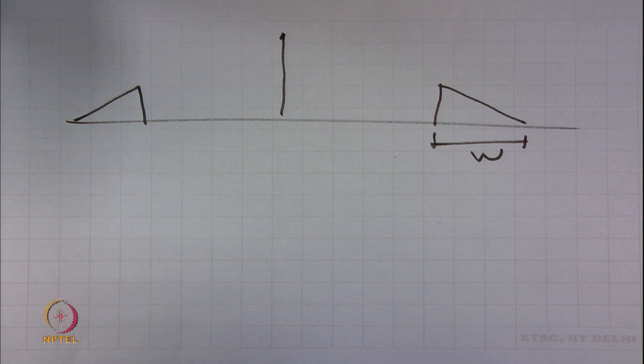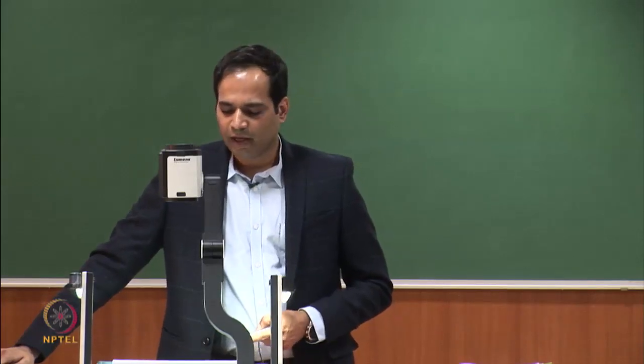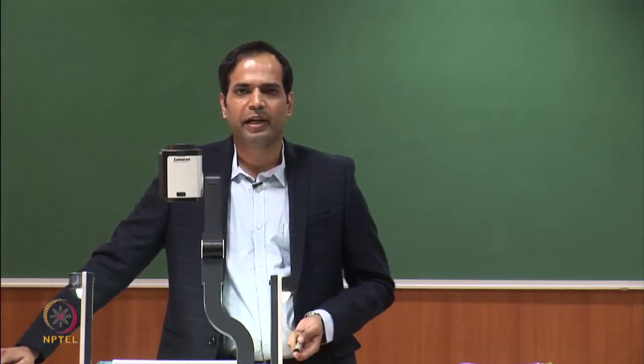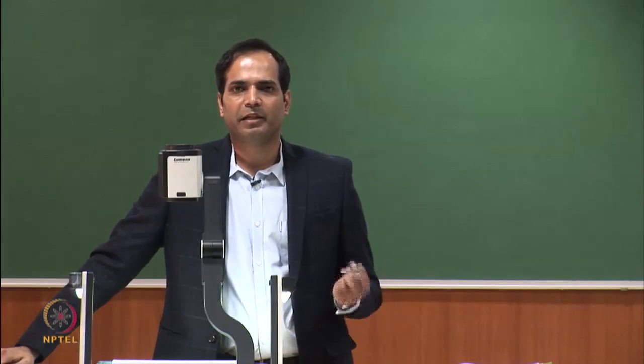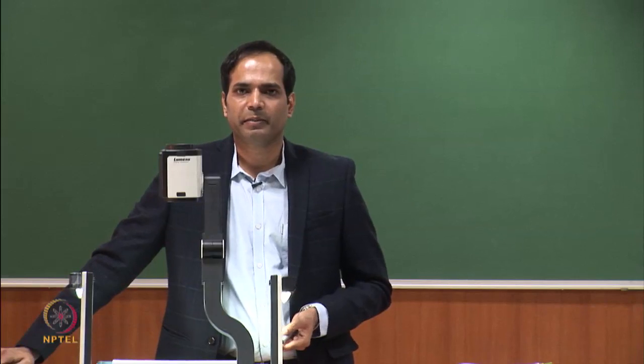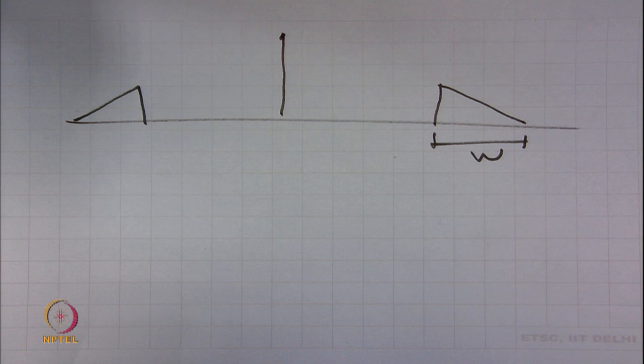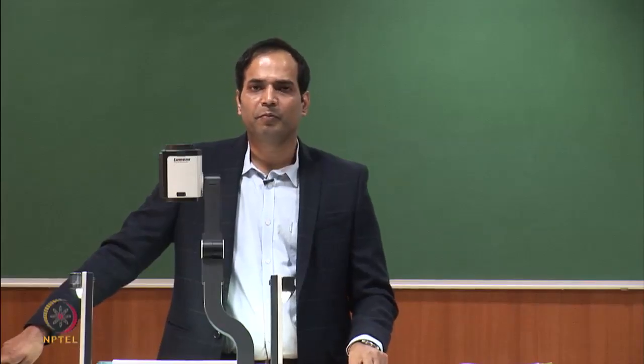Okay. So, we have developed some key ideas in this lecture. We have understood how to define the bandwidth of a complex baseband signal, we have understood how to take the inner product between a passband and a baseband signal, we have looked at the energy equivalence between passband and baseband signals, and we have also established the orthogonality between I and Q components, and the relationships between the spectrums of passband and baseband signals.